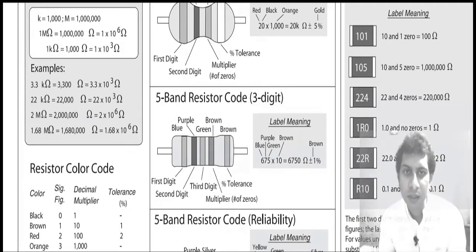For example, now if we copy their color codes from here and try to find out the value of this particular example resistor, then first is red. Red means 2. From this point, if it is 2, then make it the first digit 2. The second color is black of this band, and black is 0, so put 0. The third band of orange color will be used as a multiplier, that is, multiply by orange.